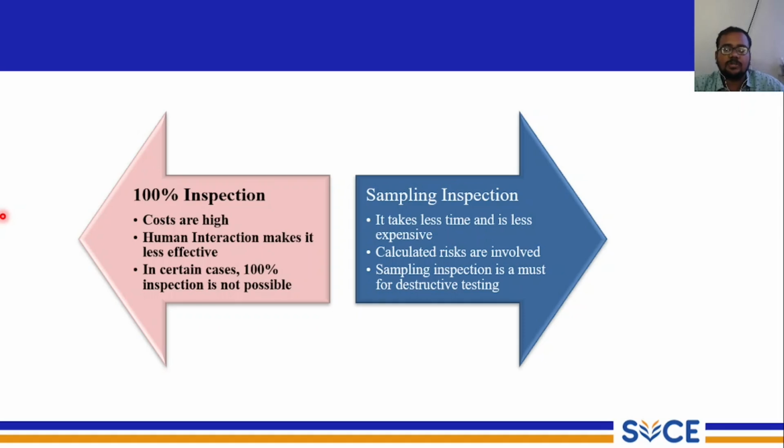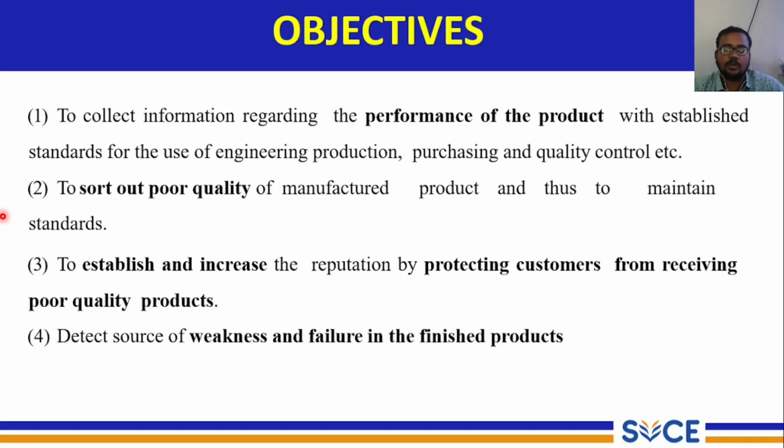So the only way of doing a safety test is to crash the car, where the product will be getting broken and will undergo destruction. So in that case, you cannot go for 100% inspection. You can only go for sampling inspection, where you will take very few samples from the lot. That will give you the overall picture about what the actual quality is.